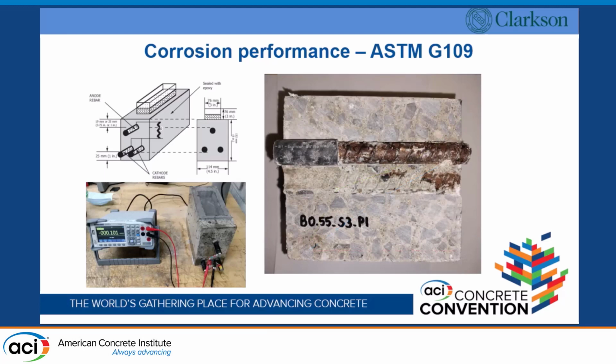We said, well, that can't possibly be happening. So we autopsied the specimen and we found brown rust. We found indications of corrosion. This is after one cycle of chloride exposure. So this tells us that something's going on here, right? That RCPT number tells us that it should never corrode because the chlorides should never get to the bars in the first place. But we're seeing something different.